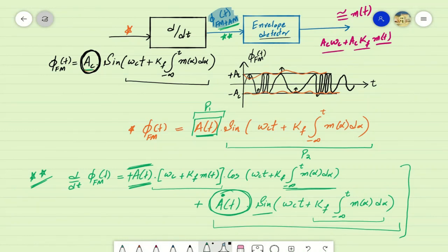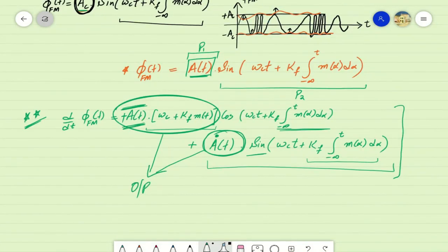After applying an envelope detector, we get envelopes jointly for both of these signals, and the output received after detecting the envelopes will be proportional to the information signal and the derivative of the time varying noise added in the peak amplitudes of the received frequency modulated signal. So ideally this part should have been a constant number while this part should not have been received.